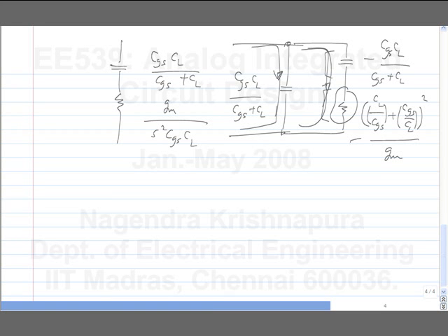So again, this also points to the fact that if CL by CGS is a large quantity or a very small quantity, then the effect of the negative resistance is not very significant. If CL by CGS is comparable to 1, you will have a problem. Okay. No, CL into CGS, I cannot compare it to 1. It is capacitance squared. It's the ratio of CL by CGS. You have this expression you must be familiar with, right? You are familiar with things like x plus 1 by x. Where does it have a minimum? At x equal to 1. Okay. So same thing here.